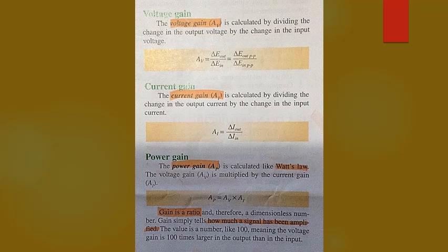Instead of having definite inputs, the output of the system or amplifier is expressed in decibels. This is a way of saying that the output is 10, 100, 1000 or more times greater than the input. A decibel rating gives relative power level and not an actual power rating.